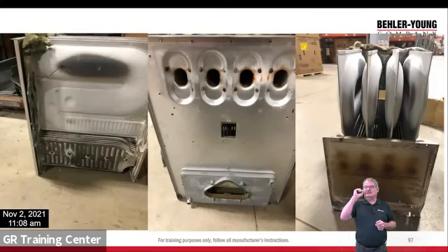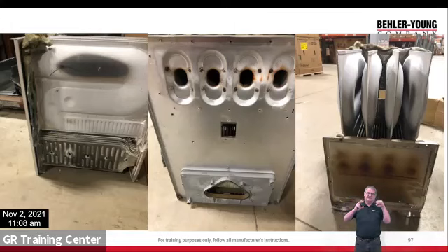This is a collector box. The gas is going to come out of the primary heat exchanger. It's going to go down to the secondary heat exchanger. The draft inducer is on the front, which is going to pull it out. So if I look in the center picture, that little triangle shape, that's where the fan would be. So it's going to be pulling the gases through. So it'll pull them through the secondary, out the vent.